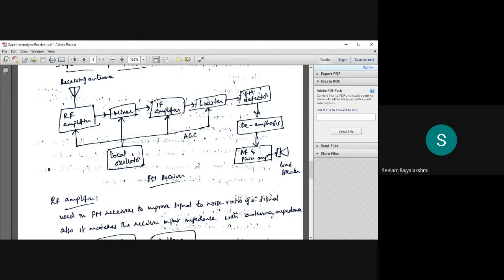Ideally, in frequency modulation the amplitude of the modulated wave remains constant. But practically, when the wave is transmitted, random noise and other unwanted signals get added to the modulated signal. Therefore, the amplitude changes. Those amplitude changes must be eliminated before the signal goes for demodulation to recover the original signal as it is.